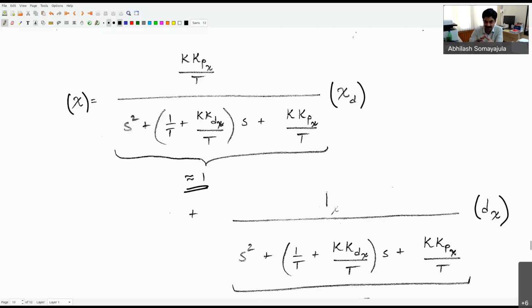So if I am allowing the control signal to take in values of certain lower frequencies of rudder oscillations and pass them down into the course angle oscillations, then any low frequency disturbances which are coming due to the wind, wave and currents are also being passed down into the course angle corrections.